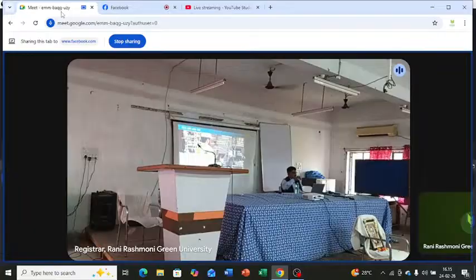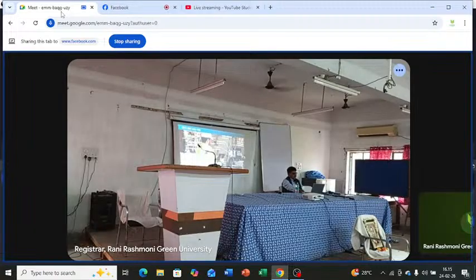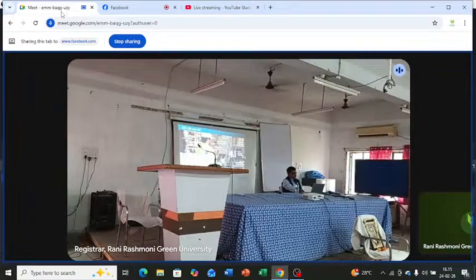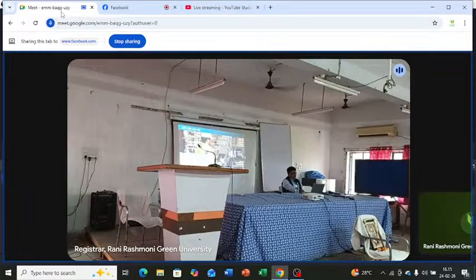Now the next upper version of this equipment, this is called RTC 360. It has both scanning and images. It has 360 degree and 300 degree vertical. That means 360 degree on the horizontal and 300 degree on the vertical. It can go up to 130 meters, and it can take up to 20 lakh points per second. So these are different levels of accuracy.